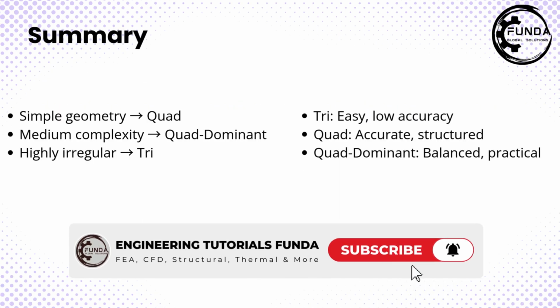Before we close, here's the rule of thumb used by many FEA engineers. If accuracy matters, prefer quadrilateral elements. If the geometry is complex, use triangular or quad-dominant. If time is limited, triangular mesh is the fastest. And in most engineering projects, quad-dominant mesh gives the best balance between performance and accuracy.